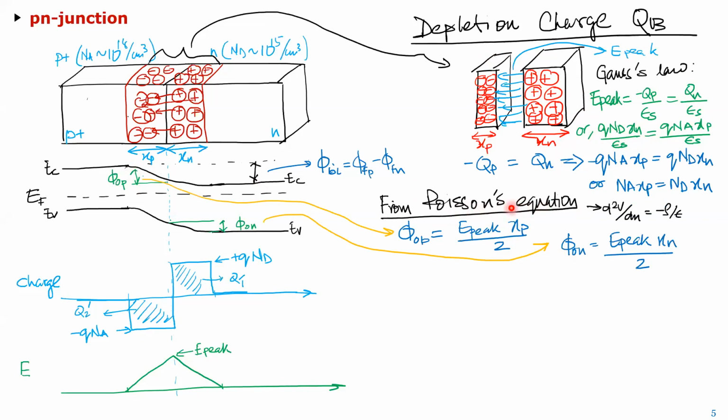Again, it's a fancy term, but it's basically if you have charge in some region. So, for example, you remember in a dielectric, we said that electric field is constant. That's because there's no charge inside it. If there was charge inside it, you would use this to find out how the electric field and the potential is varying. And that's basically this equation right here. It's basically the gradient, or the second derivative, of the potential with respect to x is the charge divided by the epsilon. It's based on Gauss's law.